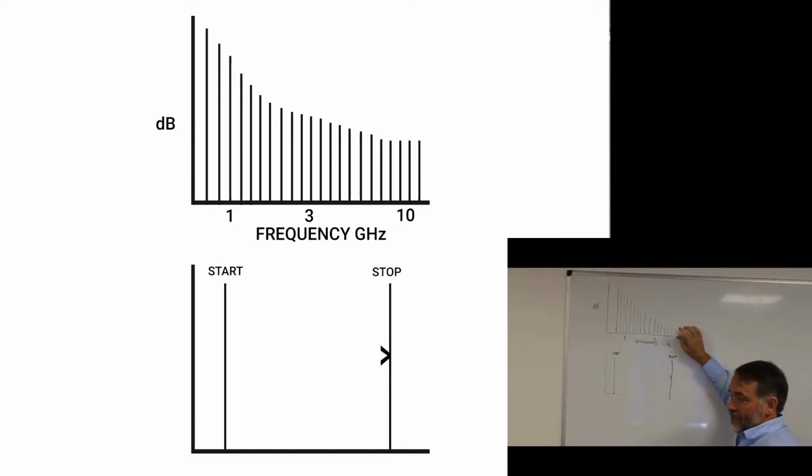It's really quite small, and so the dynamic range gets into the noise floor quite quickly. When we're making these really high frequency assessments of our network, we're not hitting it with very much signal power. But a VNA is going to hit it with the same signal power at every frequency.